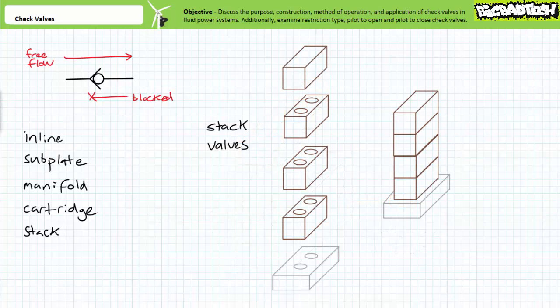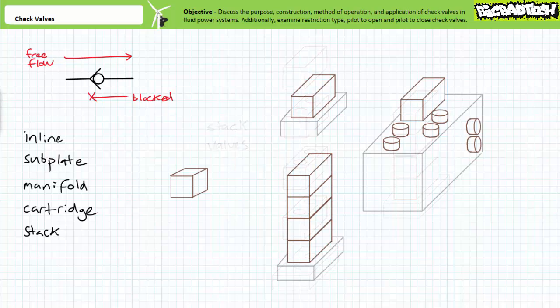Finally, stack valves use a mounting style similar to subplate mounted valves, with the exception that a stack valve is intended to mount directly to another valve rather than a subplate, the top valve in a tower being the notable exception. The connected passageways within a tower of stack valves therefore save space, reduce the possibility of leaks, and eliminate the need for external piping. Within a larger system, a combination of these mounting methods can be used.